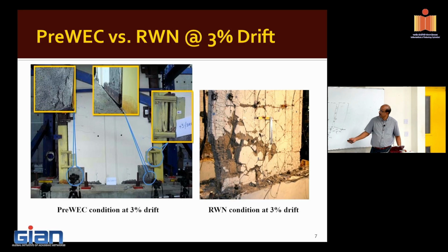And typically when a wall goes through this, if you have a floor attached to it, the floor actually gets uplifted as well, right? The floor will go up as it grows. Because of the plastification, the wall will grow vertically, and your floor will have to go for the ride as well. So you will have a system where the floor is getting elevated at the wall section, and in other places it will not be elevated, so the floor has to go through that deformation.